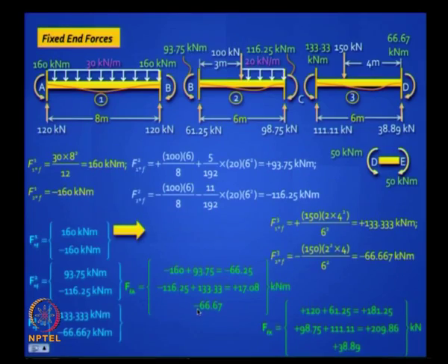FFA. FFA, the last one is you have a clockwise fixed end moment here, 66.67, and nothing else. This you need not show here, this should be thrown away. So that's all you have, and it's minus because it's clockwise. Is it clear? Actually I should not show this, but this is a carryover effect from the previous, it's already dealt with, that cantilever, that overhang is already dealt with. And I hope you are familiar with how to get FFX, it's also straightforward.